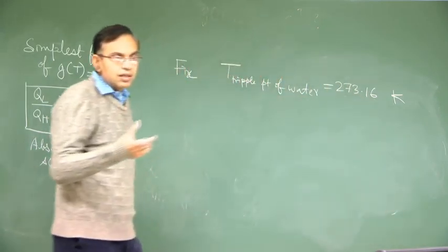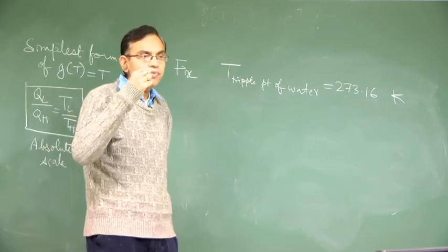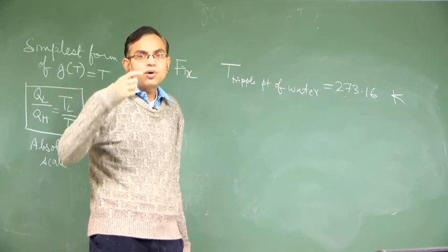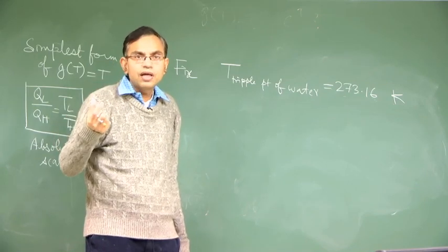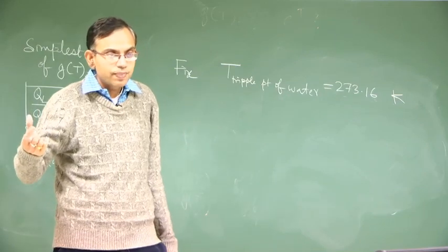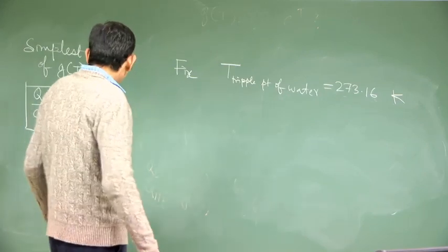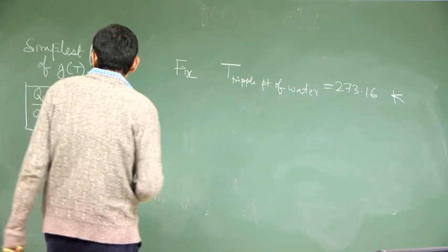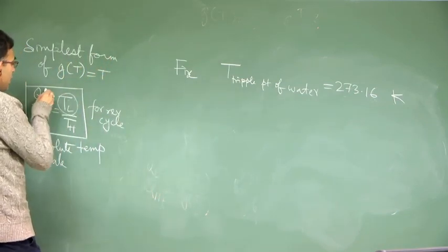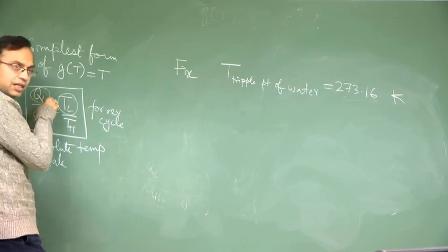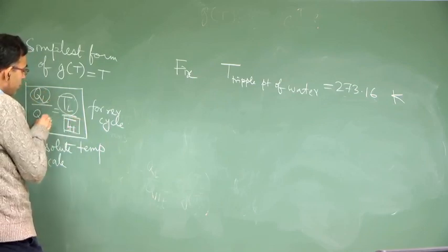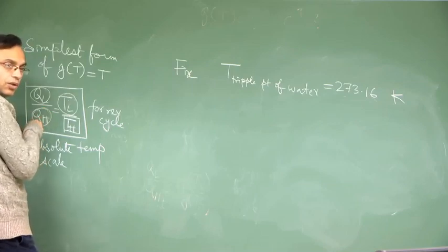That is how 1 Kelvin was fixed, and the other important constraint is that the difference between temperatures in the unit of Kelvin is the same as the difference in temperatures in the unit of centigrade. So, for example, if you could fix TL as the triple point of water and find out somehow hypothetically QL, then TH can be obtained if you can somehow hypothetically obtain QH.